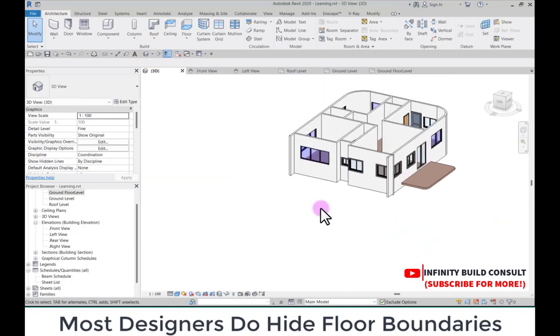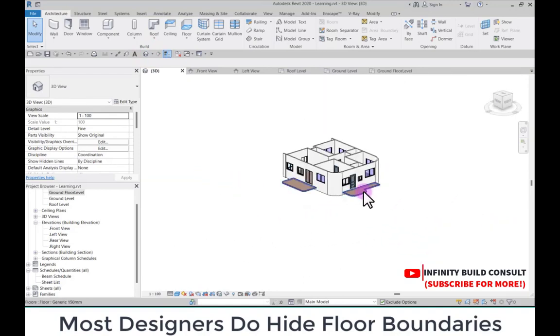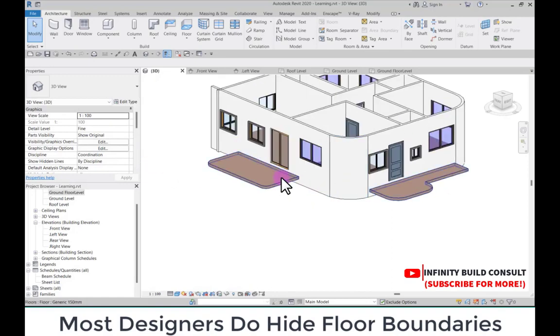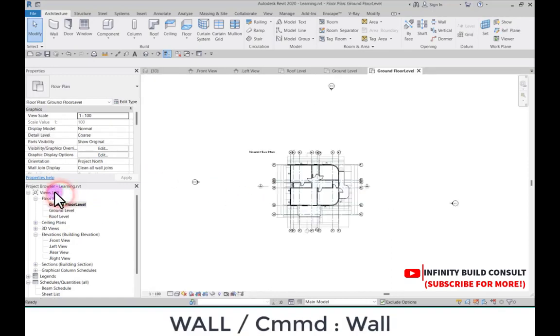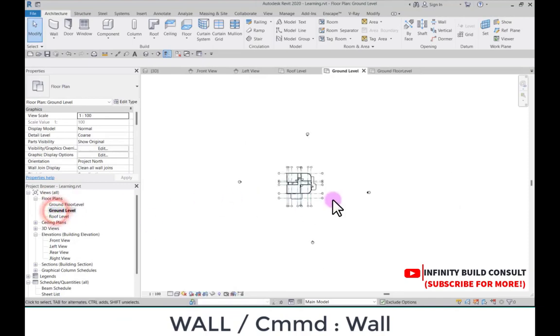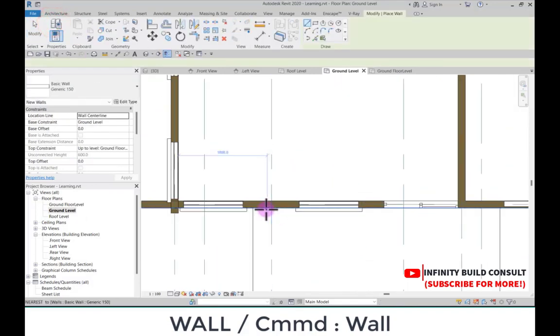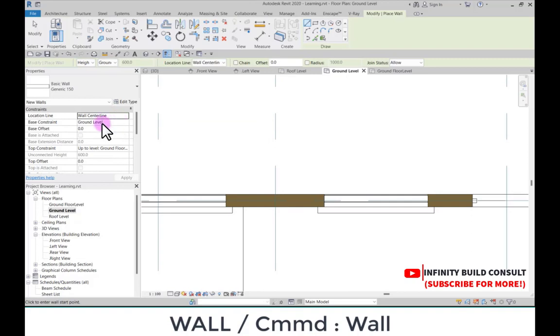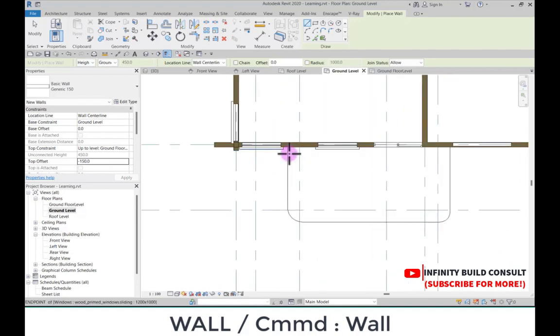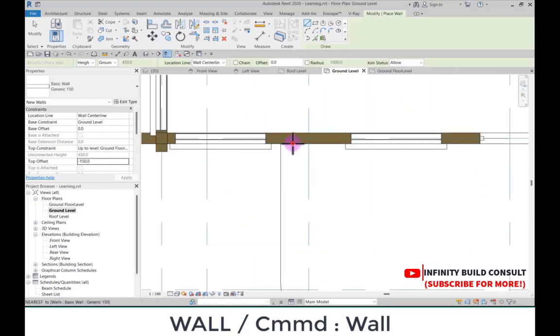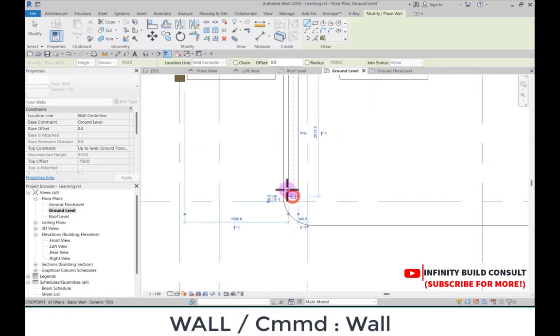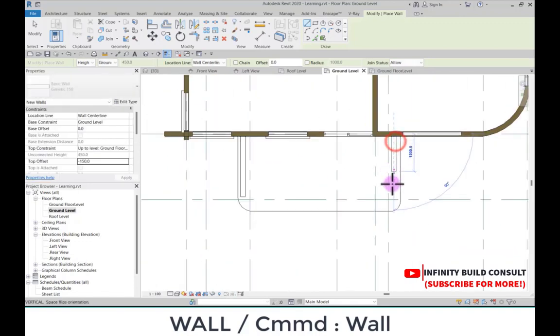Okay. So we are now going to provide walls for our porch floor. So I'll come back here and there. Or I can also come to the ground level. I think it's best. So under the ground level, I just have to set my wall from the ground level and also set this one to the ground floor. Then I can use -150. Why am I doing -150? Because the floor is -150. So I can take these ones here.